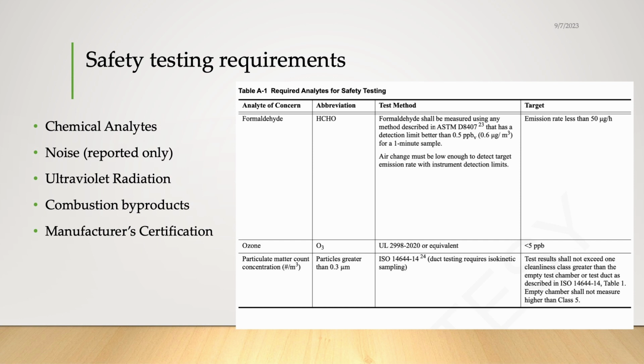Some are above 70, and if you make a Corsi-Rosenthal box, your box fan might be 90 or higher on its high speed. And what happens when you have a noisy fan? You turn it down. So the user of the standard should be aware of what fan speeds are going to result in acceptable noise levels.